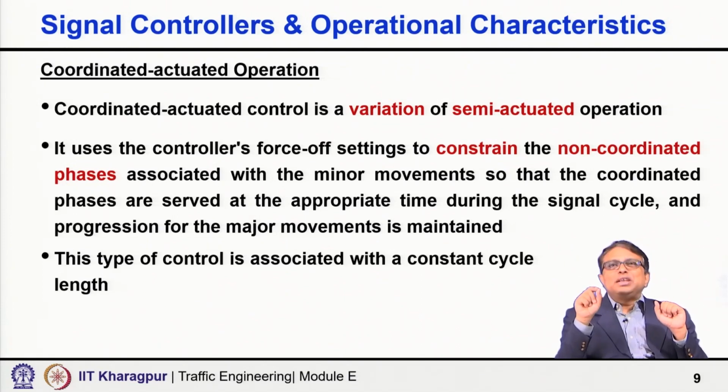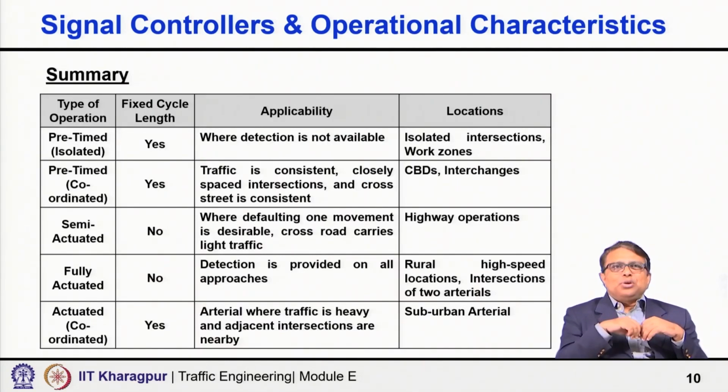But the flexibility is when and whether I will give green time, or how much green time I will give, for the minor movements where the vehicles are detected using detection, and those phases are actuated phases, correct.